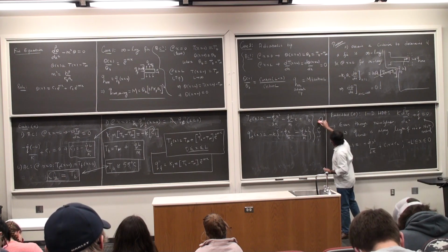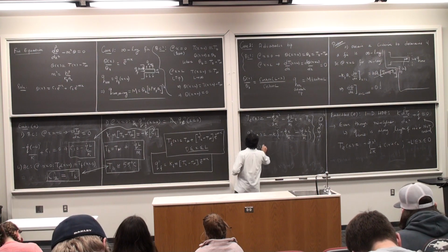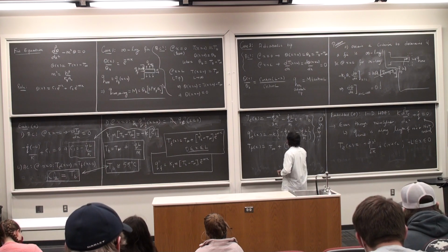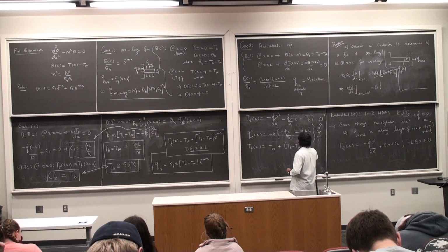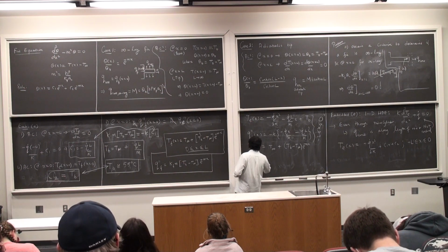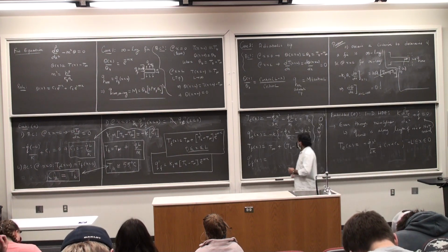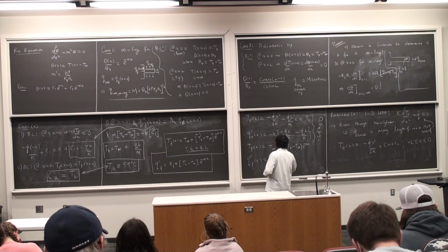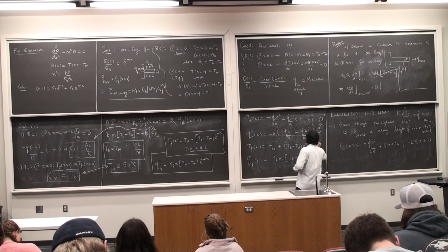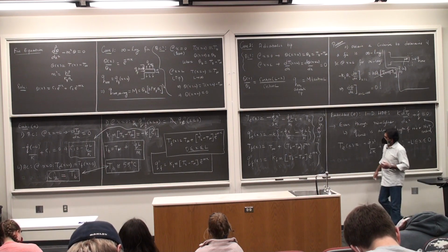In the next set, the Tf is T infinity plus Tb minus T infinity times e to the minus m x, with m being all those things that we calculated. So Q double prime f is kf times m times Tb minus T infinity times e to the minus m x, and this is for a different range of x values from 0 to L.